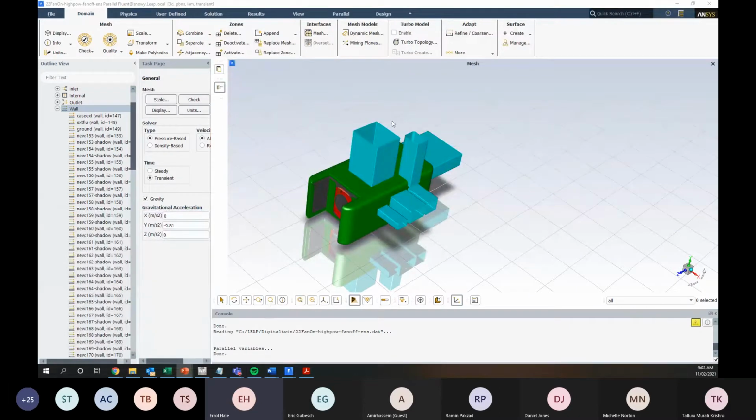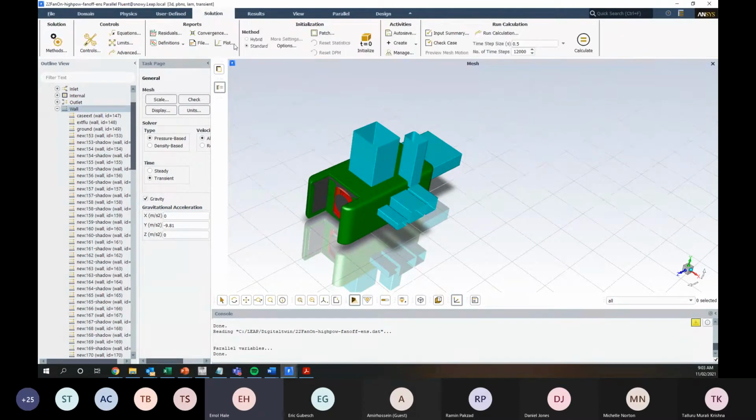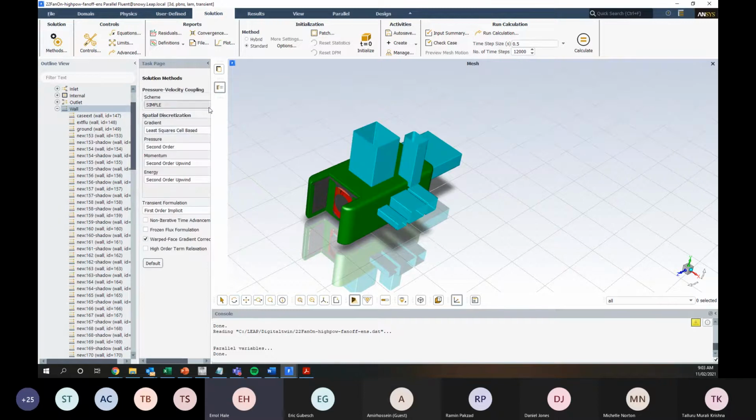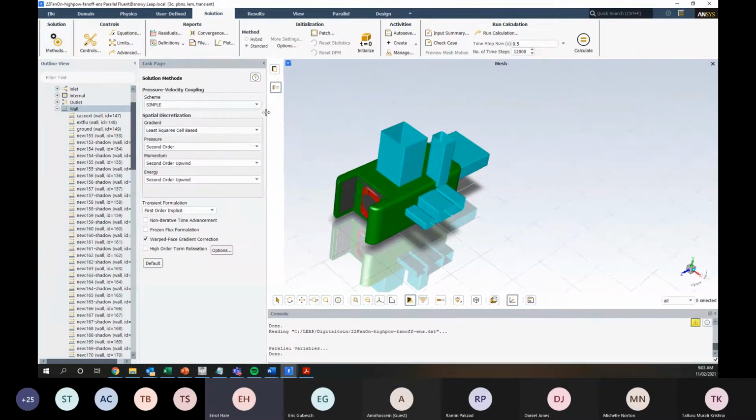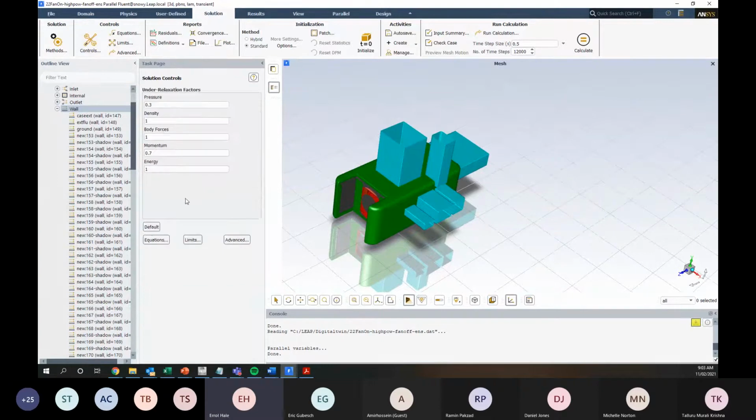So in our Fluent window, this is a case we'll be going through a bit later on. When we're talking about solver settings, we're talking about most of the things in this ribbon here. So these coupling, pressure velocity coupling, spatial discretization methods, transient formulation, and into these controls, which once again, we did speak about yesterday, but we only looked at it on here. But I'd like to go through some of it on the slides before we move on.